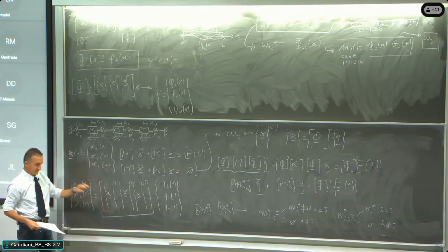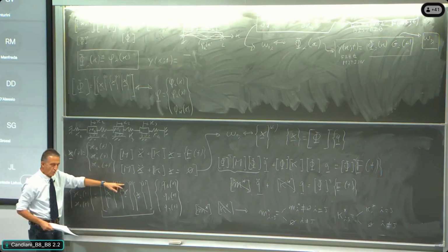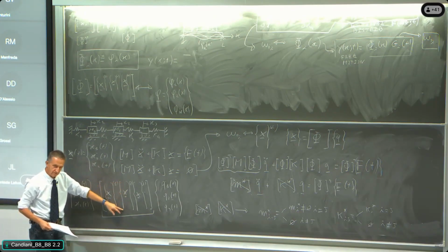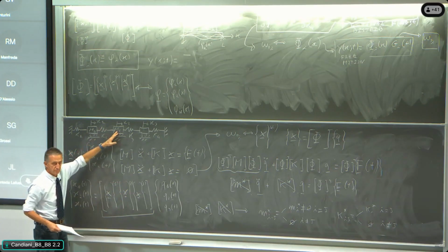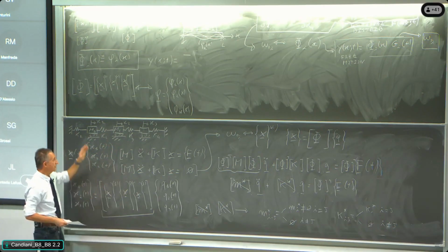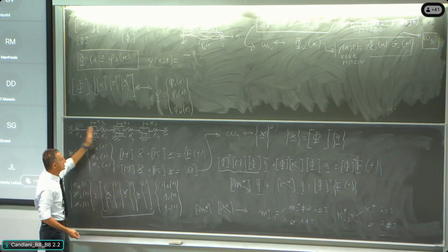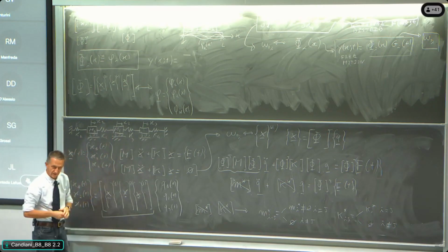But the second mode could be 1, 0, minus 0.7. So in the second mode this one goes plus, this one is almost in the middle, not moving much, and the other one is moving back. When this is moving this way, that one is moving that way, and the one in the middle is not moving much.